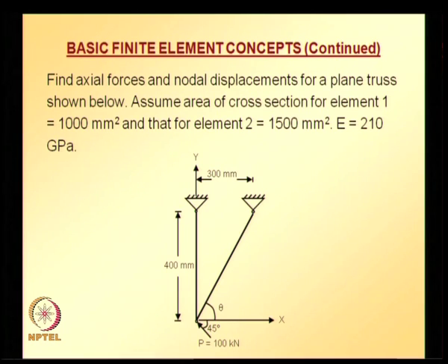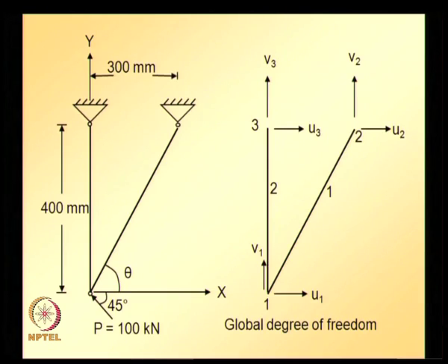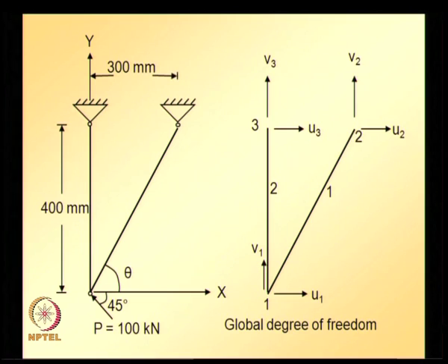For example, for element 2 if we choose first node to be node 1 and second node to be node 3, then positive direction of local x axis for this element is same as global y axis. Hence angle alpha, which is nothing but angle between the local x axis and the global x axis, turns out to be 90 degrees. However, if we choose to define element 2 to go from node 3 to node 1, then positive local axis for element is along negative global y axis, giving alpha value equal to 270 degrees. A consistent pattern for defining element connectivity is helpful when analyzing stresses with large number of elements. So the choice of local node numbers is very important.